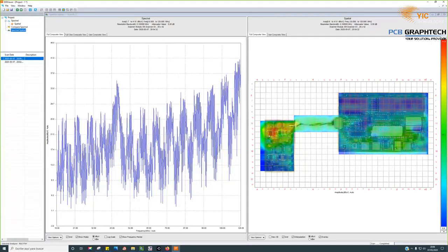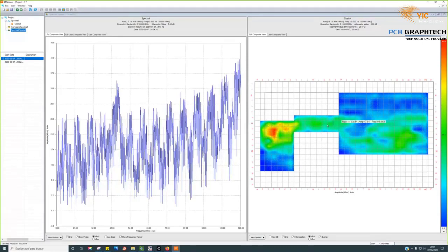And you can see exactly, this is the device and the diode that are switching to go from the 9 input volts to the 5 volts in the power supply. And you can identify that in this area here, let me remove the picture, I have green color. That means that in the cable, I have activity. If this cable is carrying 120 megahertz, and this cable is long enough, you can radiate with the cable to the environment.